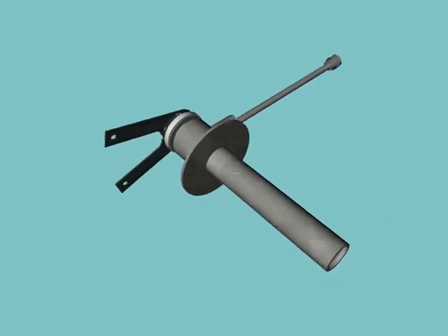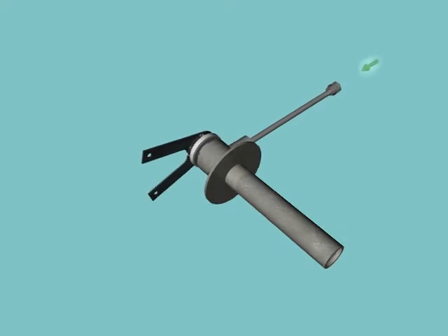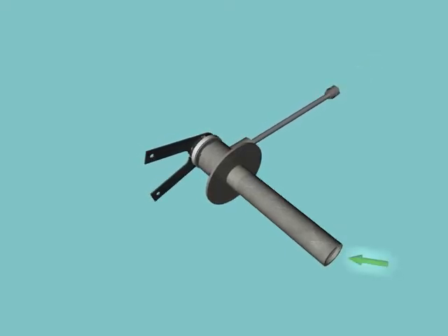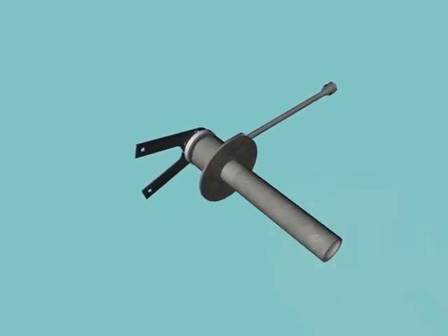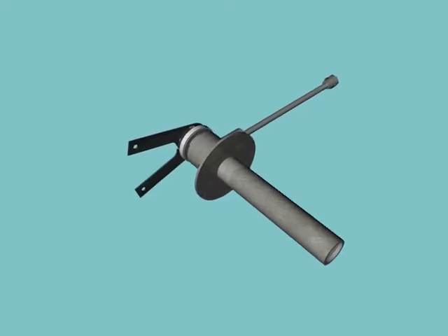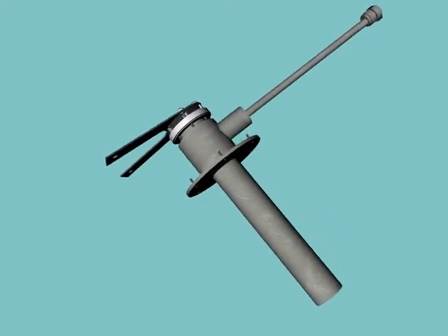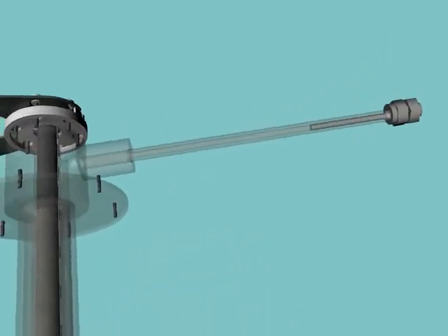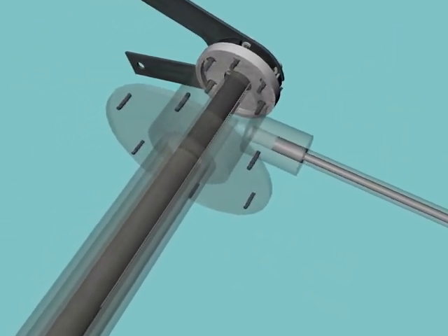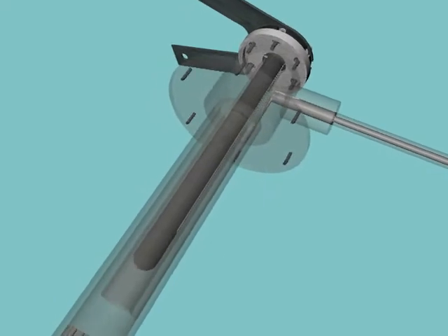In short, liquid lithium is injected from the feed system into the feed tube. The lithium flows through the cathode where it's being evaporated and exits through the cathode tip in gas form. Here you can see the path of the liquid lithium that starts in liquid state and ends up in gas form.